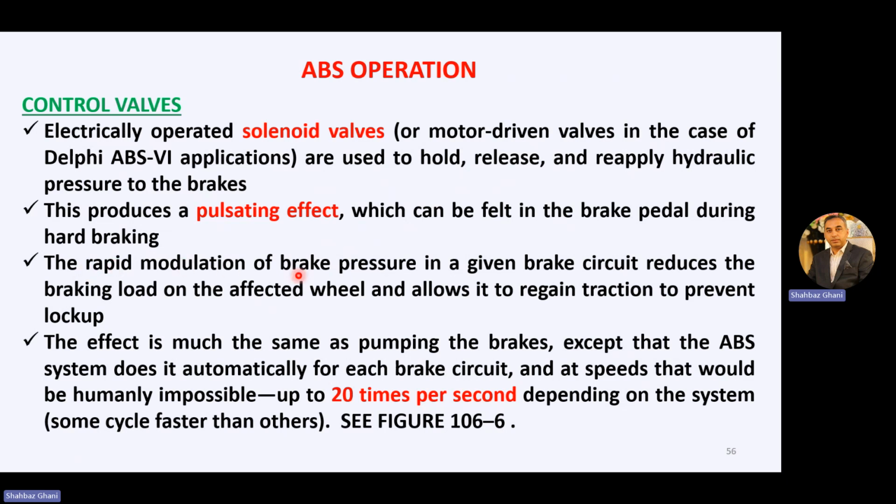The rapid modulation of brake pressure in a given brake circuit reduces the braking load on the affected wheel and allows it to regain traction to prevent lockup. The effect is much the same as pumping the brakes, except that the ABS system does it automatically for each brake circuit.